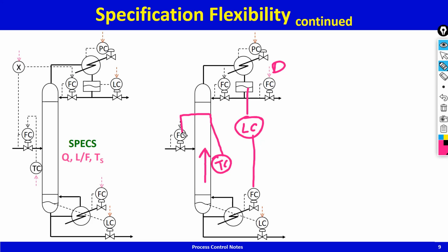And so if the distillate rate is increased, you start sucking in more feed. So that's how this thing is going to work. And dynamically it is fast because level goes down, increasing the steam will cause an immediate increase because vapor will reach in a few seconds to the top. On the other hand, liquid reaching down will take many minutes.